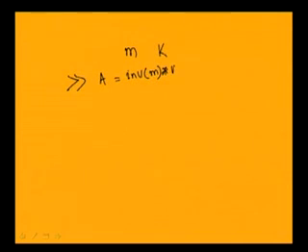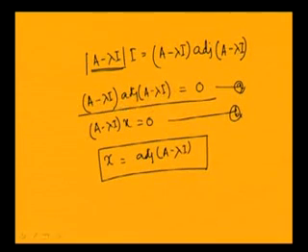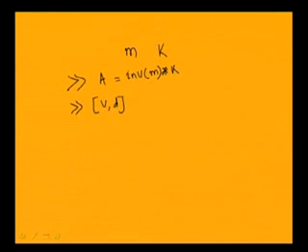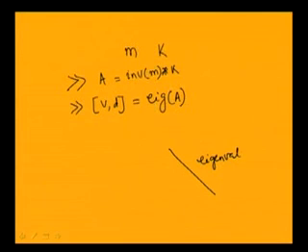This will give you the A matrix, and then you just write [V, D] equal to eig(A). This will give you the V matrix and D matrix. D will contain the diagonal elements, and these diagonal elements are the eigenvalues of the system. And V will contain the eigenvectors.